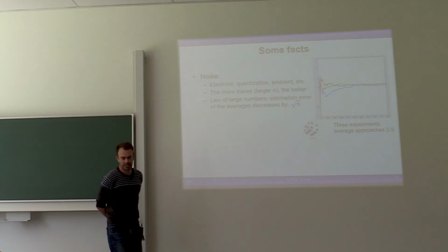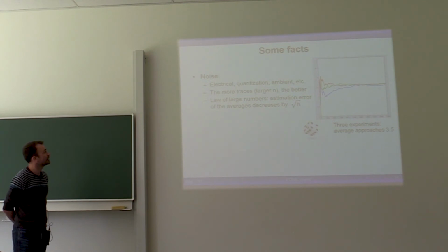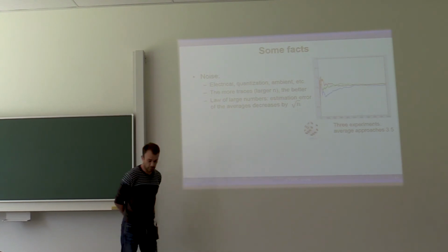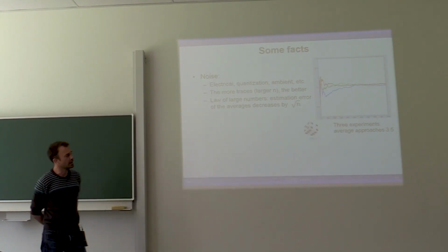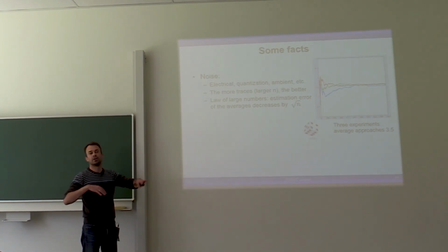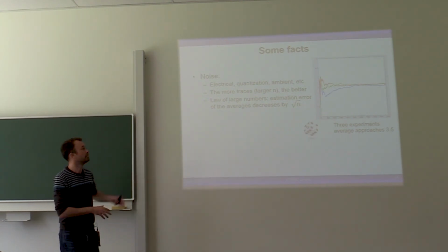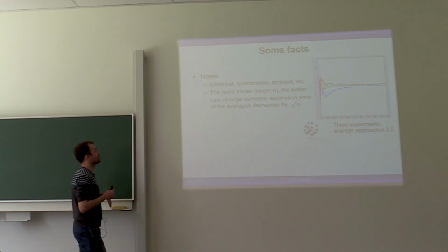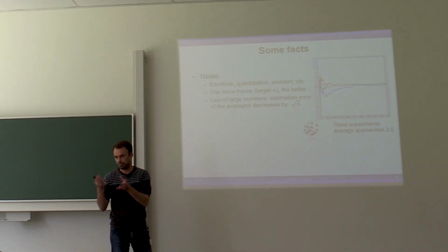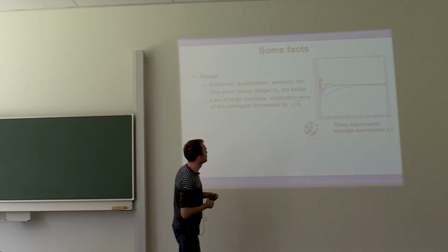So just a few, let's say, more practical things. The whole process is highly empirical and sampling based. So one of the many things we have to deal with is noise. There's lots of noise. There's electrical noise in these measurements, because when it says this is 5 volt, it's not exactly 5 volts. It's something that fluctuates maybe very narrowly around 5 volts. So we have electrical noise, we have quantization noise, so the oscilloscope that turns some power consumption into a number that I can process. This is quantization noise. This is not a perfect process.